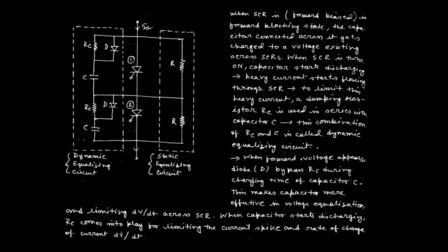When the anode current starts flowing, as the capacitor is there, the capacitor will be charged fast. At first, if thyristor 1 and thyristor 2 are both in the forward blocking state, a small amount of leakage current can flow across the string, but as it provides a huge amount of resistance, the current first tries to flow through the capacitor, then the thyristor.